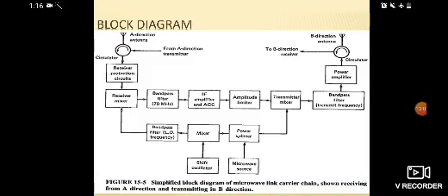So for that reason, we have to convert to the intermediate frequency, then only it can be processed and given to the amplifier. Okay, so in this case also the frequencies would require microwave frequency amplifiers, but they are very costly and very difficult to maintain also. So for that reason, we convert into an IF signal in the range of 70 megahertz, and this can be done by using a mixer and a local oscillator.